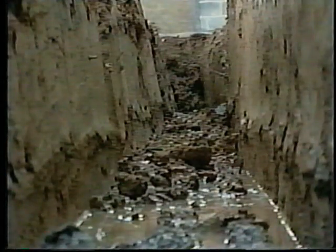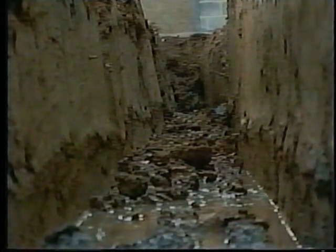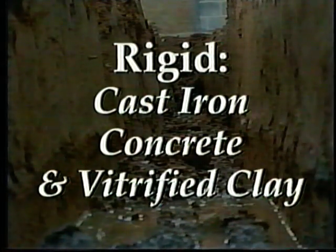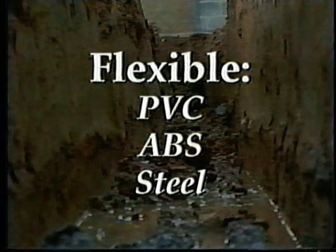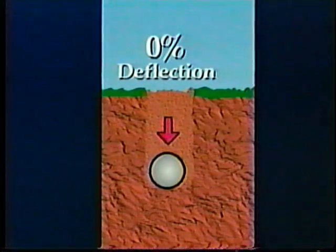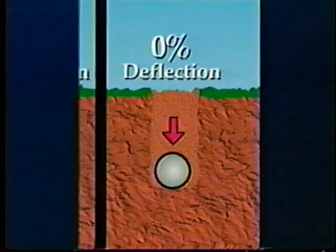Pipes for underground installation are generally classified in two ways. One is rigid, which includes cast iron, concrete, and vitrified clay. The second classification is flexible, which includes PVC, ABS, and steel. Rigid types are expected to support the anticipated earth and live loads with little or no deflection. These types of piping depend upon strength, rigidity, and stiffness to maintain their structural integrity.